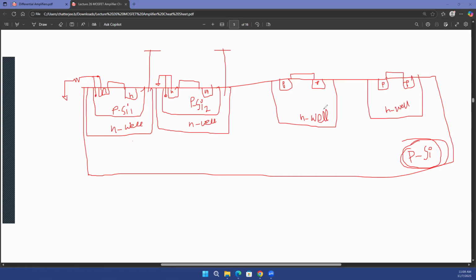Okay? PMOS needs to be inside an N well, whereas NMOS does not need to be inside these two levels of isolated N wells and P silicon. If you're paying more, this can be done. But if you don't want to do that, if your application does not demand that, you are going to have that body biasing effect.